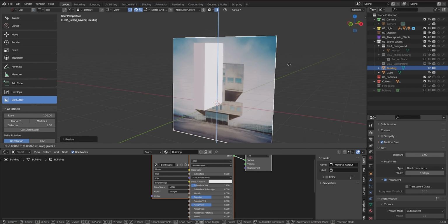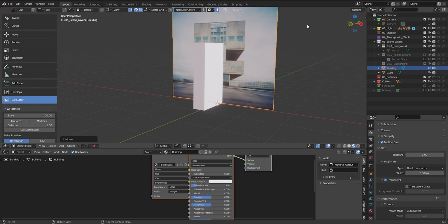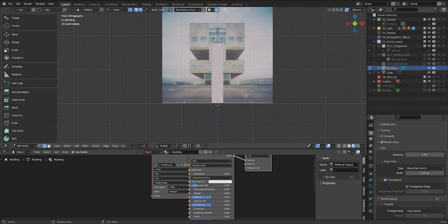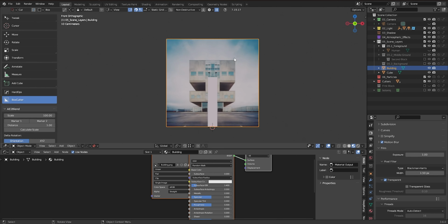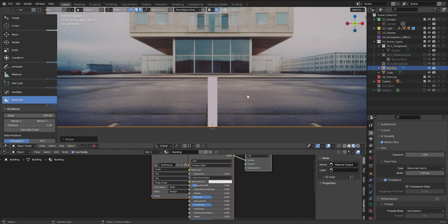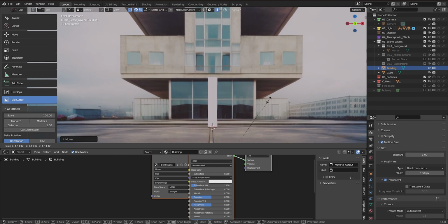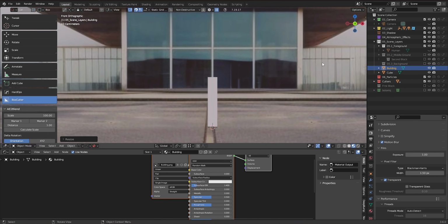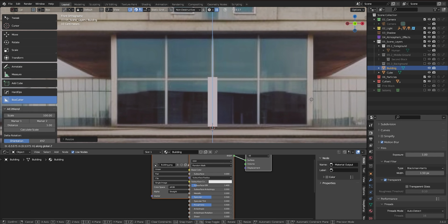Then I'll take here my image that I bring from Midjourney. I'll come to the edge, click here on the edge, then I will press Shift S, Mesh Machine, Machine Tools actually, and I'll bring the object origin to the edge. And then I press 1, 5 to remove the perspective, and I'm going to scale this till I get the proper scale of the building for a human. So let's go like this, G, Z, still not the size that I need, a little bit higher, like this and like this. Actually, let's go even further like this. I think probably something like this.